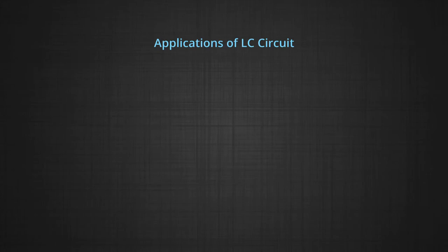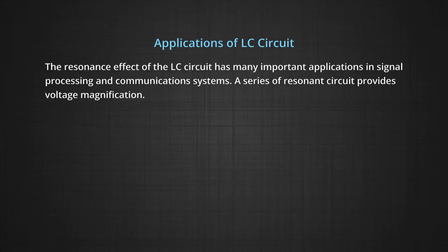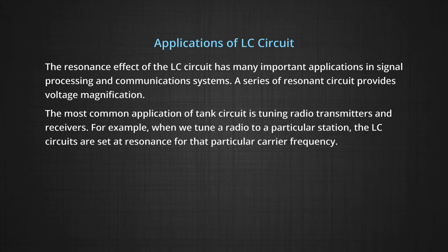So, here we can talk also about what the applications of LC circuit are. As the resonance effect of the LC circuit has many important applications in signal processing and communication systems, a series resonant circuit provides voltage magnification. The most common application of the tank circuit is tuning radio transmitters and receivers.